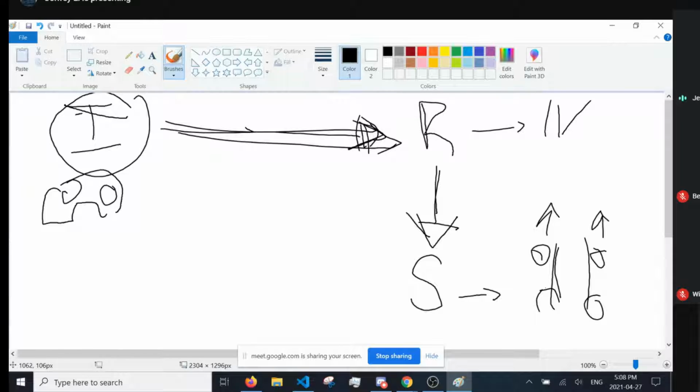This is called an open loop system, where the only thing that's happening is we're taking our inputs from this side, and we're using only our inputs to decide how to actuate the rest of the system. And it's open loop because information, data, is only flowing in one direction, right? So it's starting from our inputs over here, and then it's flowing to our robot, and then from our robot it's affecting our state, but nothing is being put back in the system. So why is open loop control not necessarily optimal, right?